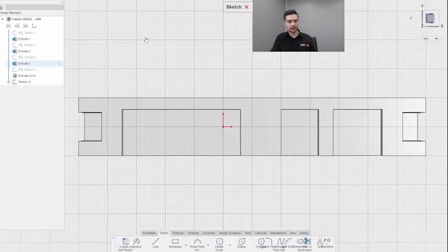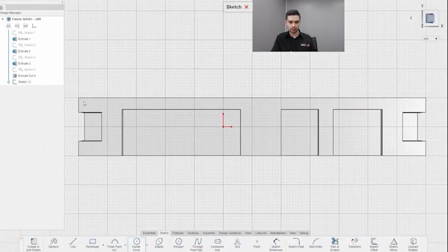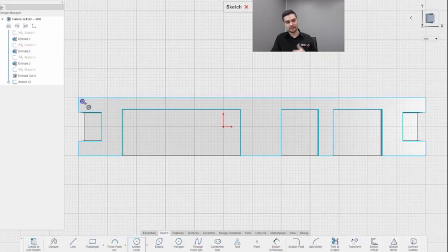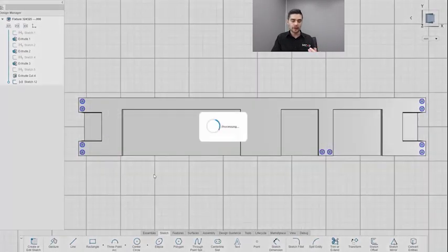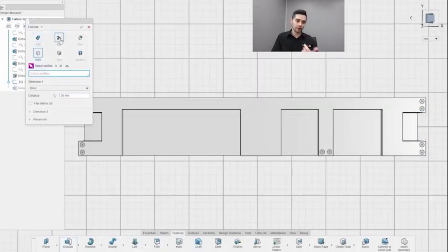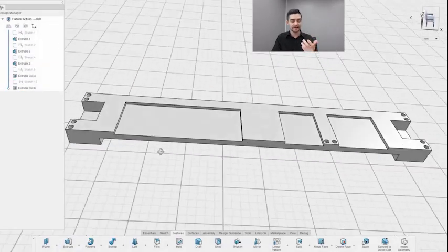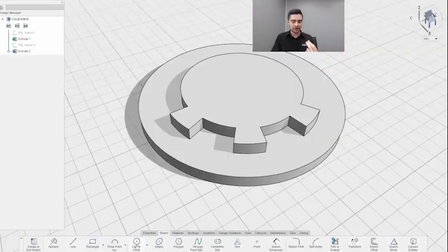So if we start a sketch on this face, and we put a circle in one of the corners, if we ask the design assistant to help us with this, with the sketch helper, it's going to select similar corners that it wants to put them to. We didn't add dimensions, we didn't add references, it just bases it exactly on its distance from similar geometry.